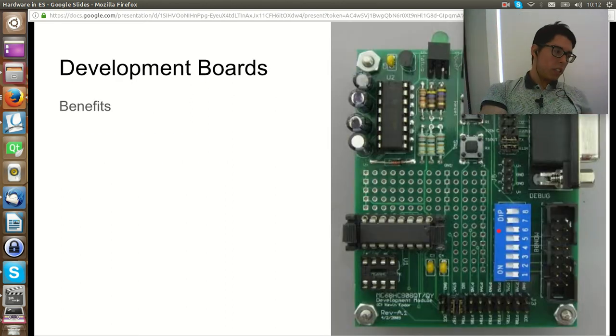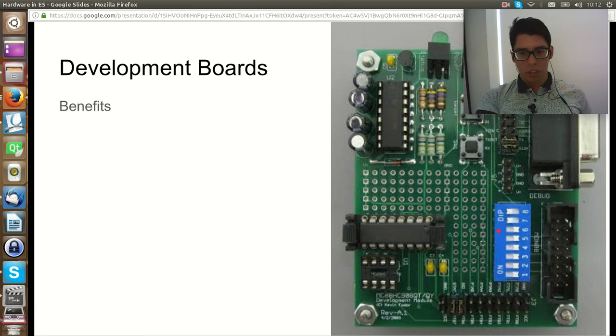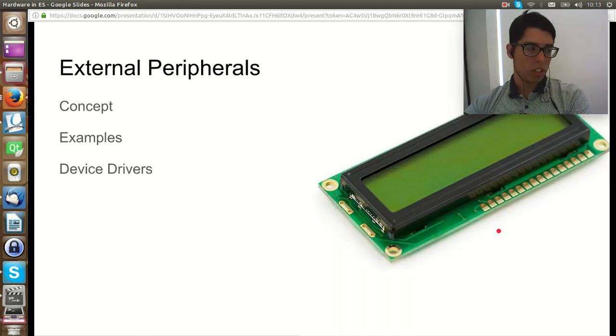We have also the topic of development boards. Some benefits are that development boards help you to understand peripheral functionality. Also, the boards typically include software examples that can get you up the learning curve a lot faster. Another benefit of development boards is regression testing. This means that if you are having some odd issues in the environment, you can go back to the development board, where supposedly the hardware is stable, and debug the application.